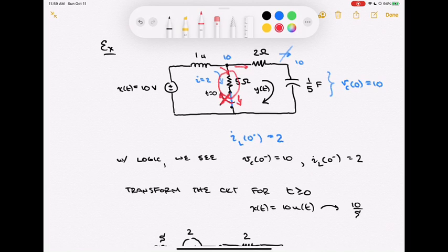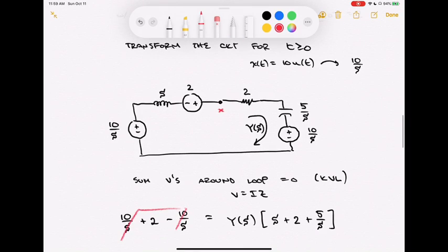I also could have taken that differential equation and applied a unilateral Laplace transform to it and solved it in the transform domain. Instead, I ended up just transforming the circuit. That helps me avoid the step of needing to find the differential equation. It allows me to incorporate those initial conditions in a very explicit and easy way, and I can solve it all in one step without any kind of calculus, without finding the unit impulse response, without any of those hard things. I just end up doing something algebraically. I did a little bit of pre-work up front to find out what the initial conditions were, which was generated because of that switch inside this circuit, and then unilateral transformed that, and I got a simplified circuit that explicitly incorporated things like initial conditions.